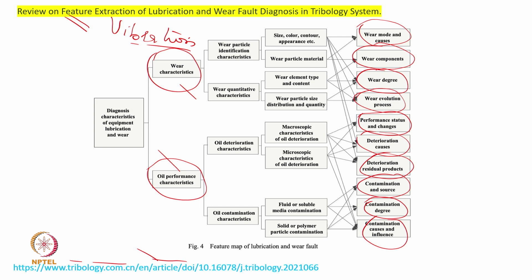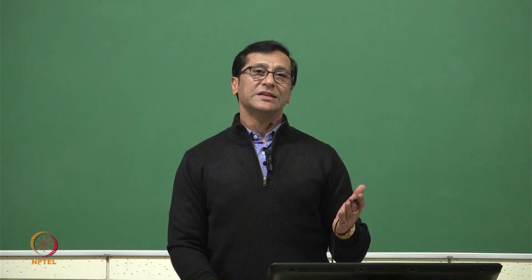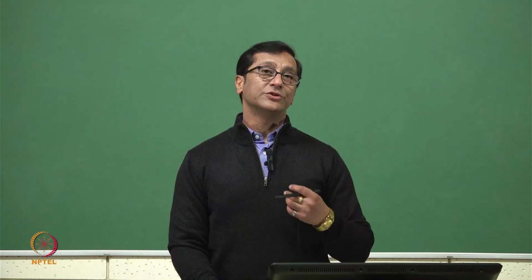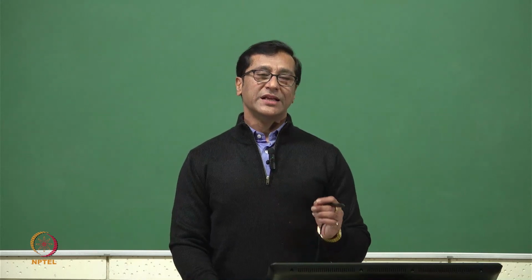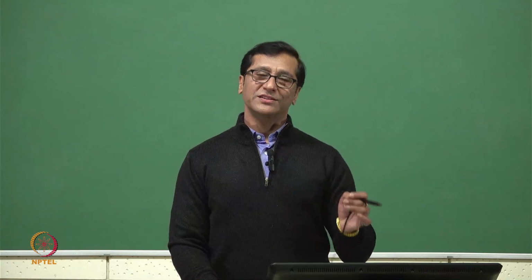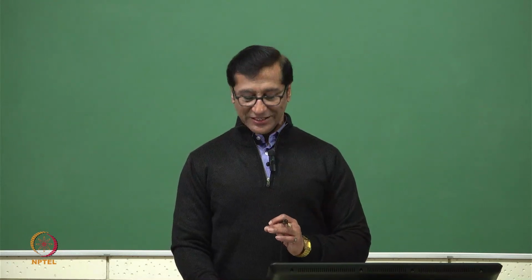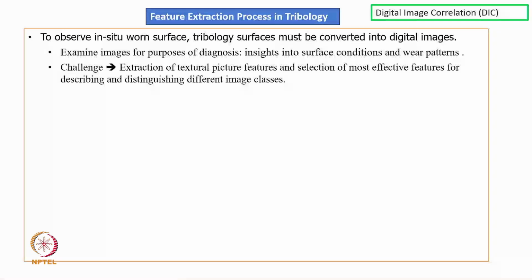Now it depends, every author has a different way, every expert has a different way to extract the features. It is basically expertise based, basically domain knowledge based, and what we want to achieve. So feature extraction from one author to another will vary, but techniques will not vary significantly, which we are mentioning here. Wear analysis, oil analysis, vibration analysis is not going to change significantly from one author to another in this situation. Now we try to summarize this. We say feature extraction process in tribology.